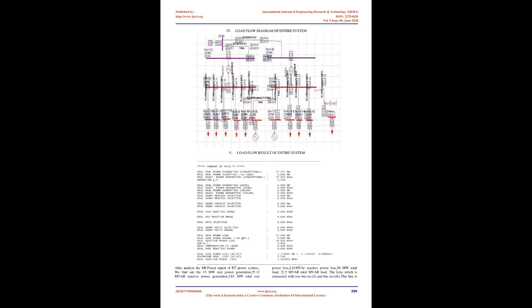3. Switchyard 66/11 kV. The 66 kV incoming line is coming from GETCO. There are 2 step-down transformers of 30 MVA. The transformers step down the voltage to 11 kV. Here the 11 kV line is supplied to bus 1 and bus 2.